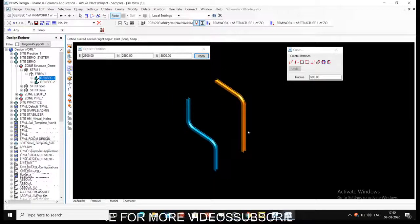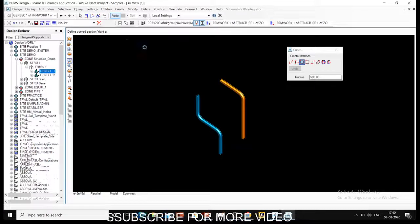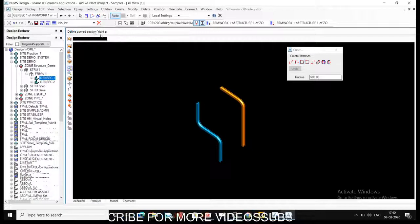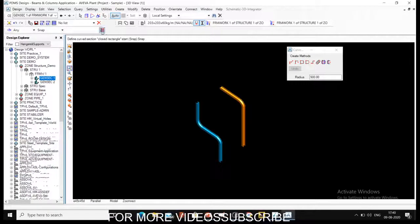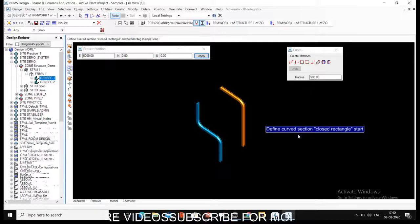Okay, so let us go for the rectangular section, the closed rectangular section. It will prompt to create a start point. I will go with, let us say, 5000 in east, so that it will be created somewhere here. That is my start point for a rectangle.